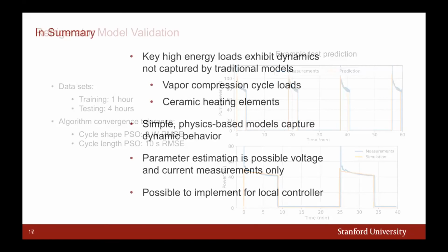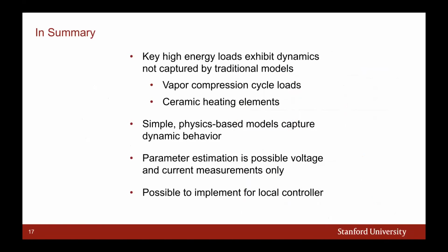To conclude, we demonstrated that key high energy loads do exhibit dynamics that are not captured in the traditional load models. We focused on vapor compression cycle loads and ceramic heating elements. We demonstrated that simple physics-based models can capture these dynamics, and that it is possible to run parameter estimation routines based solely on voltage and current measurements, which makes it possible to potentially implement for a local controller in the context of distributed energy resource control. Thanks everyone for listening.